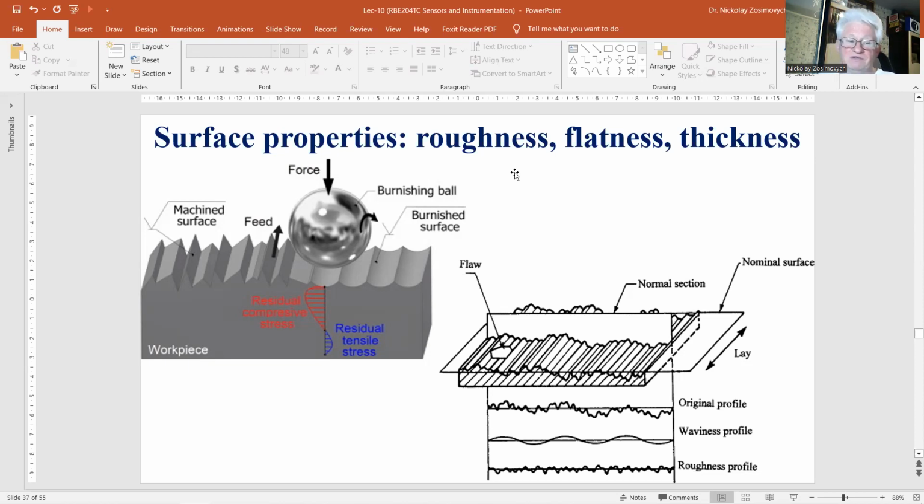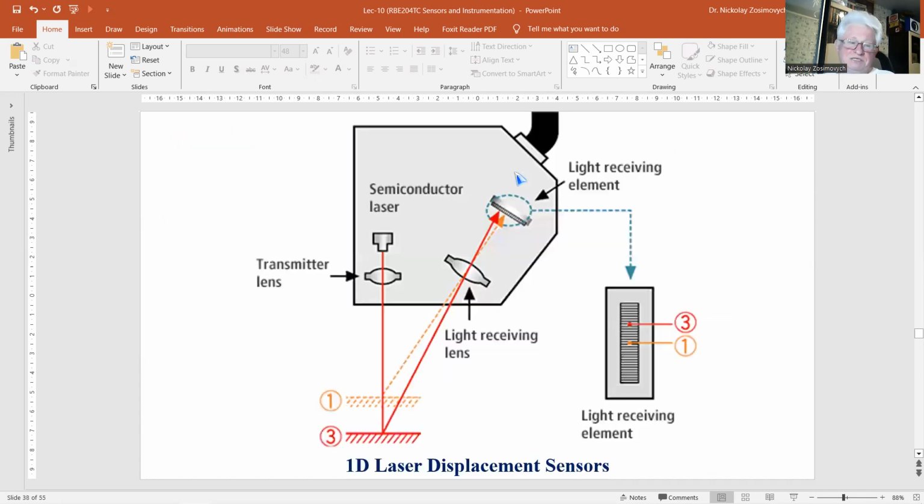A line scan camera with 2048 pixels views the strip in perpendicular direction, so it receives a light spot of about 10 pixels in width. Using a special algorithm, the resolution is increased to an equivalent of 0.1 millimeter in the height of the steel plate. Position or displacement sensors that are intended for a very particular application may be redesigned to serve other applications in mechatronics and quality inspection.